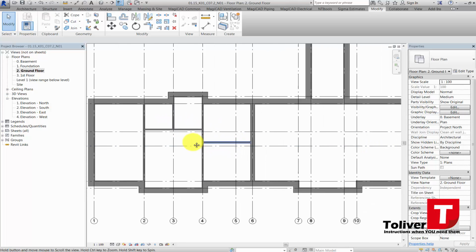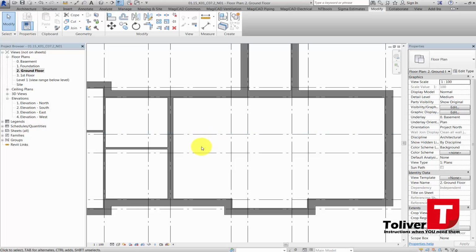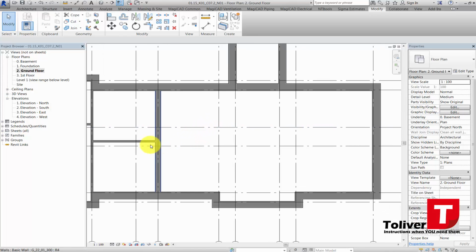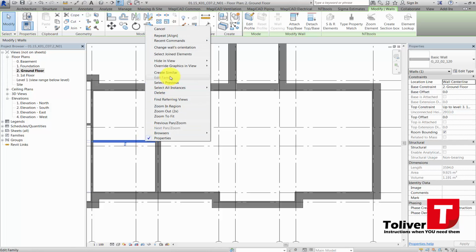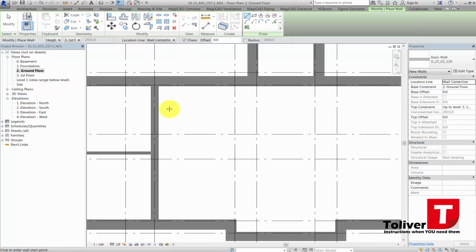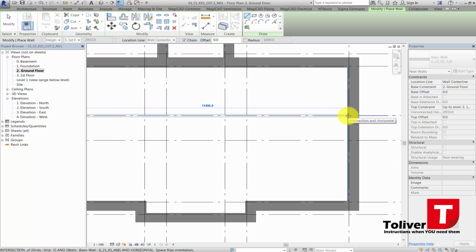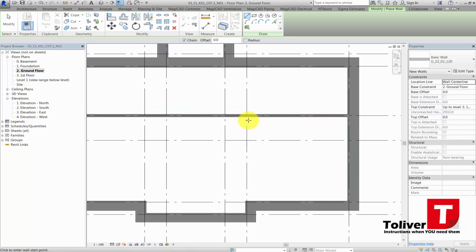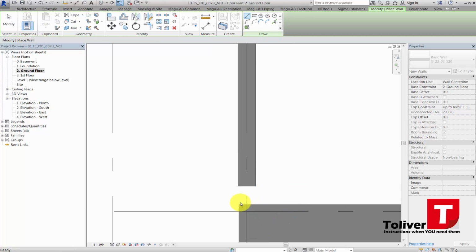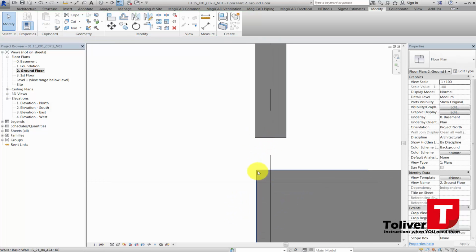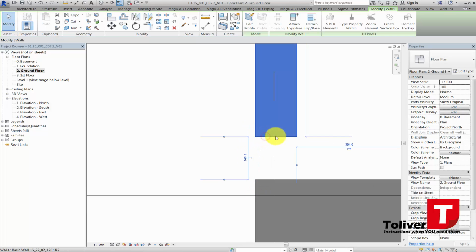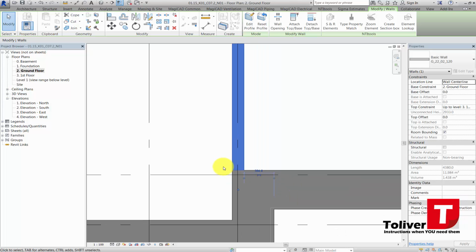So do we have our walls over here? Yes, we do. I'm going to be going over here now, and I'm going to be doing the same walls. So I'm going to choose this one, right click, create similar, wall center line. I'm going to have a wall that runs from here all the way up to the opposite end. I'm going to have a wall that runs from here and down to there. Again, do not connect it, because then you're going to have a problem. Align it, you are allowed to. Do it like this and then drag it down to it so it connects.